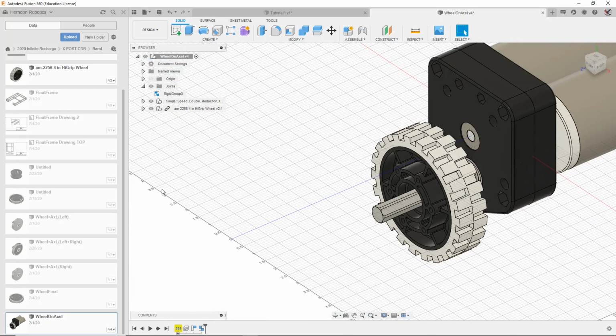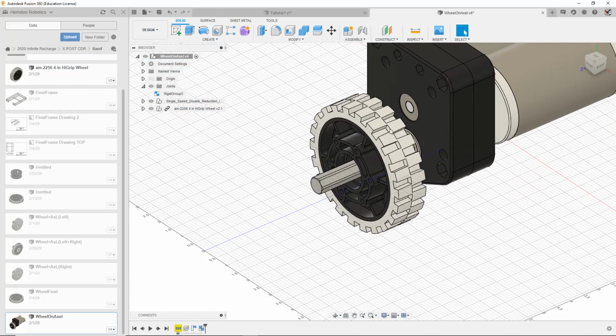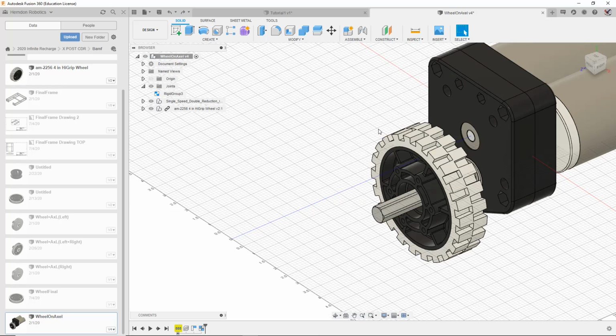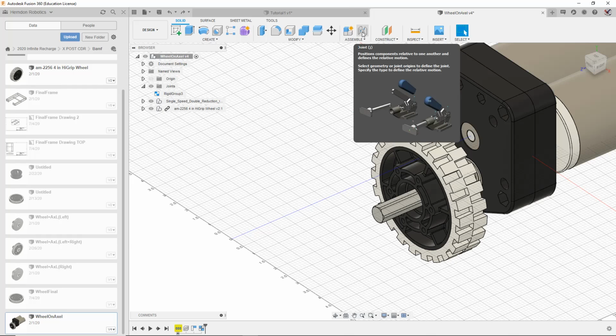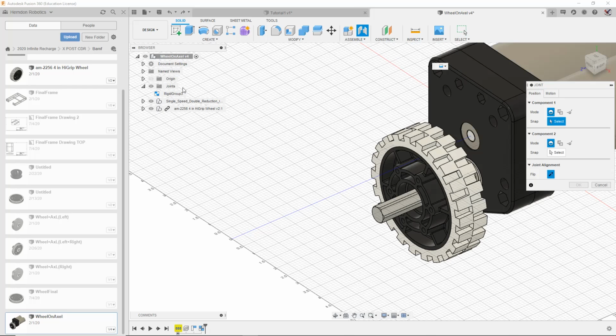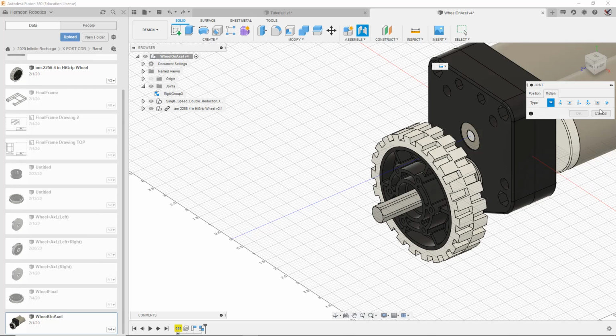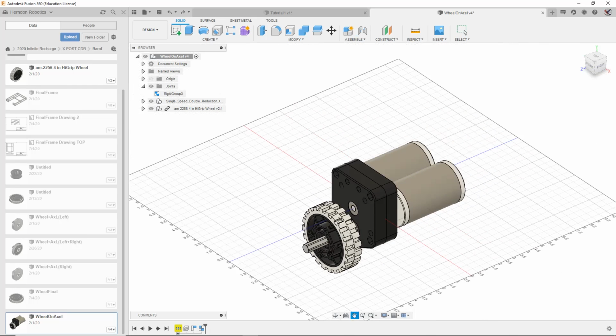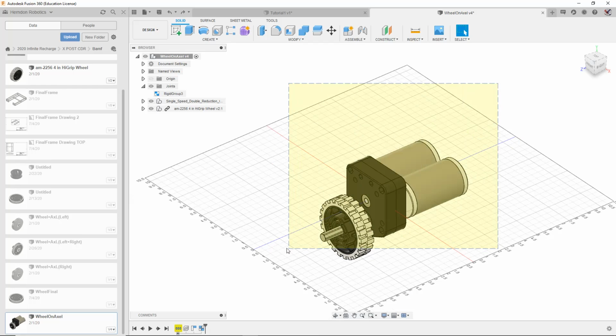We're just going to hit OK, and now there's a rigid group, so if we move this, they're the same. And it was the same thing with the wheel. If we move them, it's the same. The wheel just allows movement, because Fusion, once again, is a very professional program. If you want to show animations and stuff like that, that's how you do it. Where was I? You can do the same thing in Joint by selecting two things and then just clicking rigid. However, rigid groups allow you to select up to anything you really want. You can create a bunch of stuff.